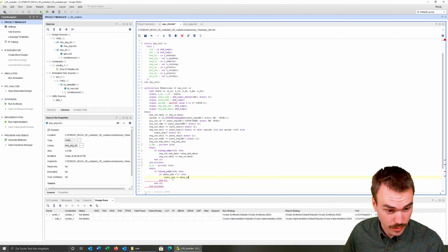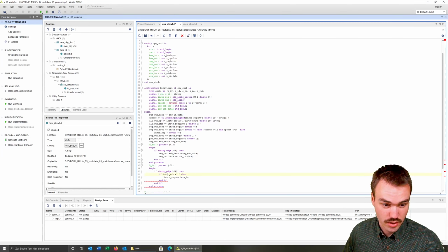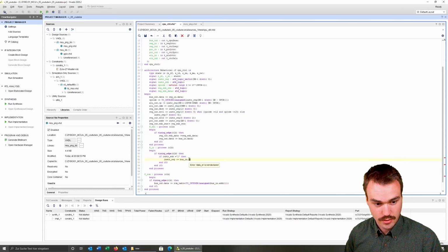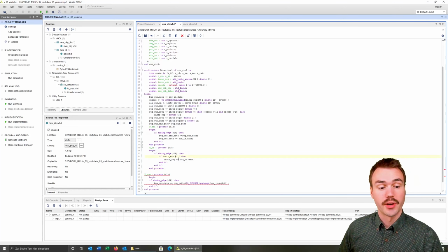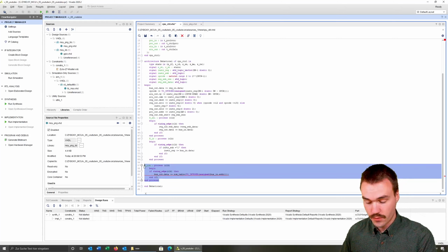So we look that always in the instruction fetch that then the instruction register is written here. So we make sure that then the instruction enable is 1. And here actually it's bus in the data. Yeah, so we always want to make sure that when we are in the instruction decode state, that this instruction enable is set to 1. So now we are already able to implement our finite state machine.